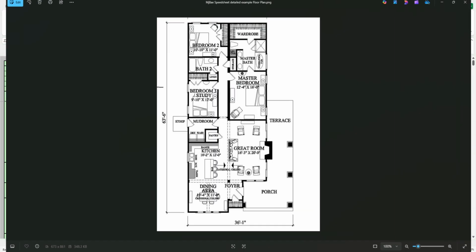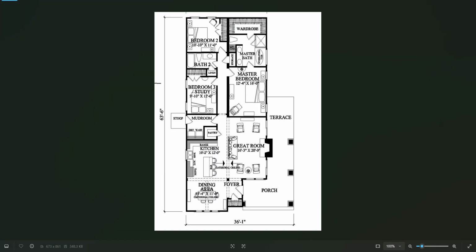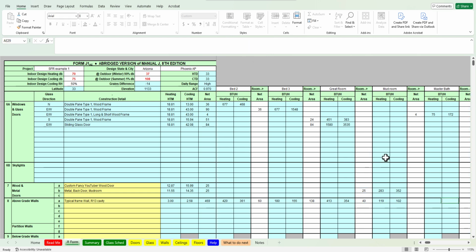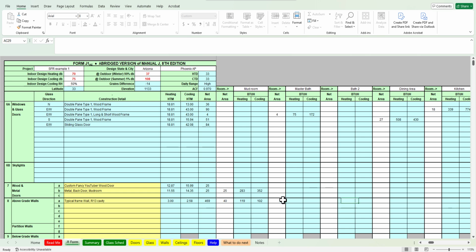All right, next on, we've got the mudroom. The mudroom is, well, they don't give us a dimension. Let's use our imagination. It's probably about 8 feet. Okay, let's go with 8 feet. Could be smaller, like 7 feet. Let's go with 8. So it's 8 times 8. That's it. Oh, it's got a door. I need to amend my formula, so I'm up here in the formula bar. So minus, and it's got this door here.